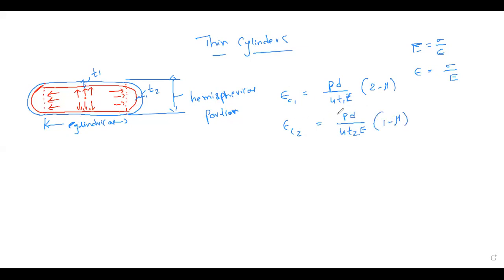From this only we have derived that the thickness of the hemispherical portion will be 0.5 times the thickness of the cylindrical portion. How have we derived this? There is a statement: in order that there is no distortion in the member, the member is not under failure.